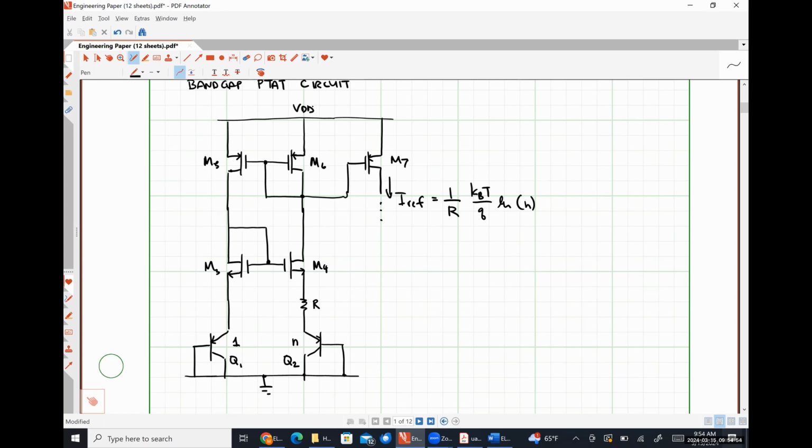This is a simple version of it. I saw a paper from MIT about a much more enhanced version of this that would take probably 3 pages for me to draw, that managed to achieve less than half a microamp of stability over a 100 degree C change in temperature. So they can get incredibly stable if you're willing to add subsequent stages and all of this kind of good stuff to take that into account.